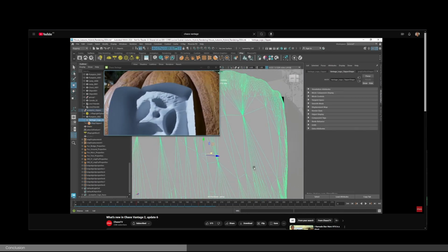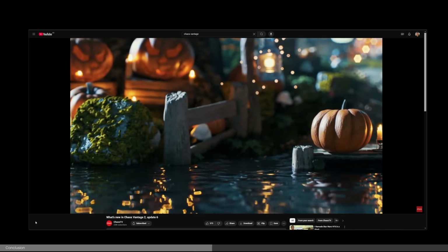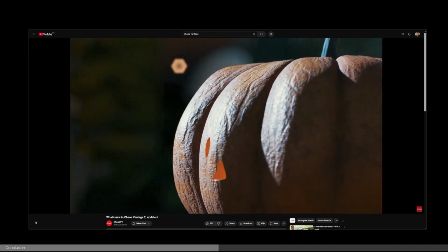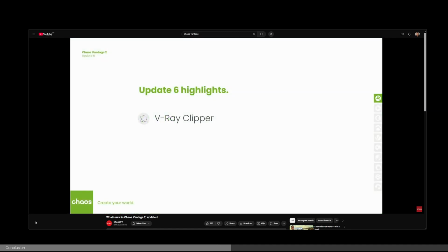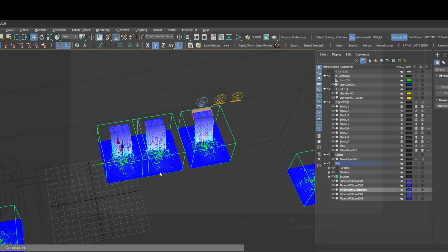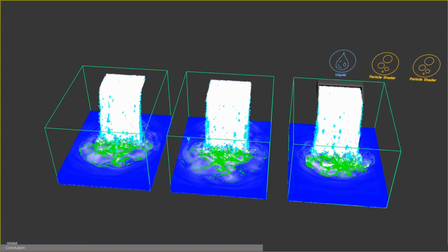But as I mentioned, merging multiple oceans isn't supported. It is a slow process, and as you know, Vantage is built with speed and interactivity in mind. For that reason, this setup needs to be modified slightly if you want to render it in Vantage. The last thing is that for the ocean surface to be properly generated in Max, the simulation grids shouldn't overlap. You have to keep them separated and leave enough space where the stitch will happen.